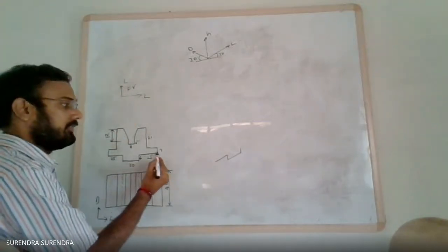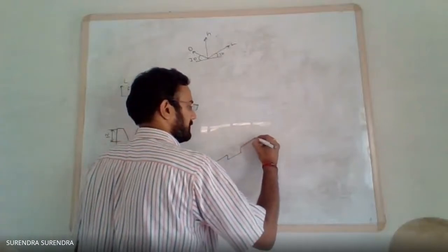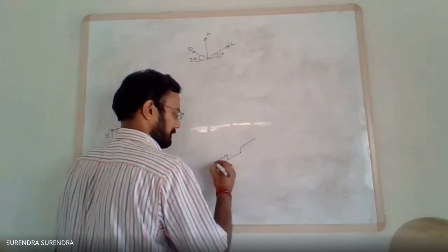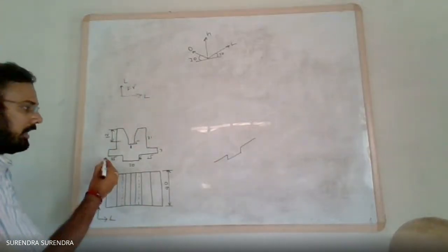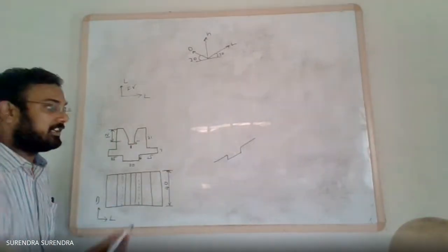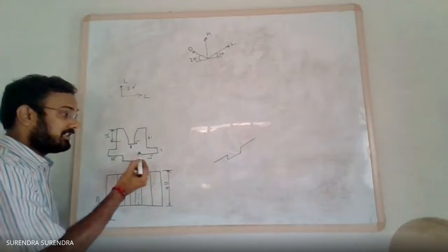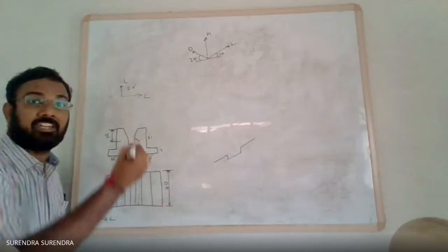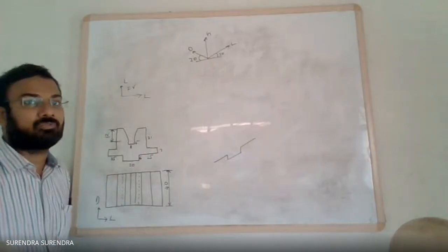Next a 25 mm long line. I draw this shape in isometric. Observe that I drew the horizontal lines at 30 degrees inclination. Vertical lines stay vertical, do not rotate them. Keep the vertical line exactly vertical.